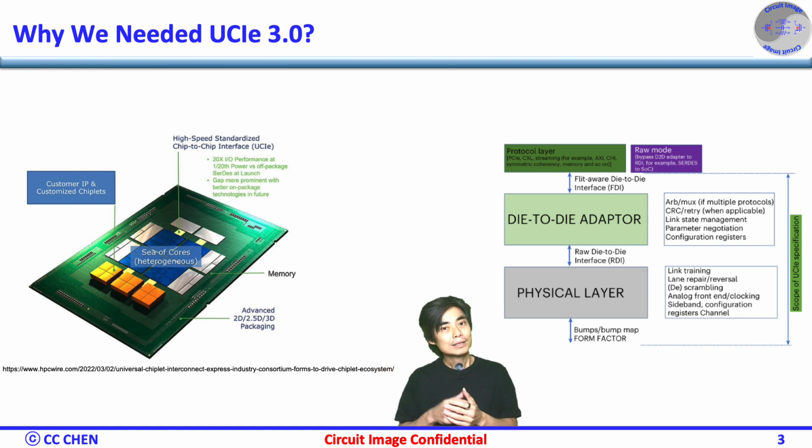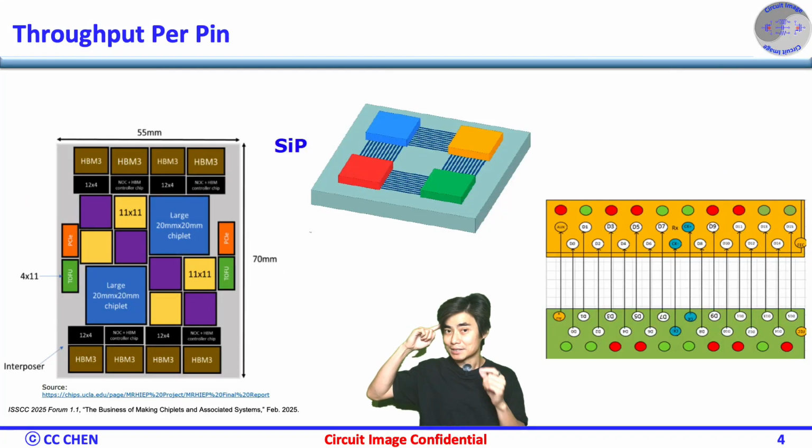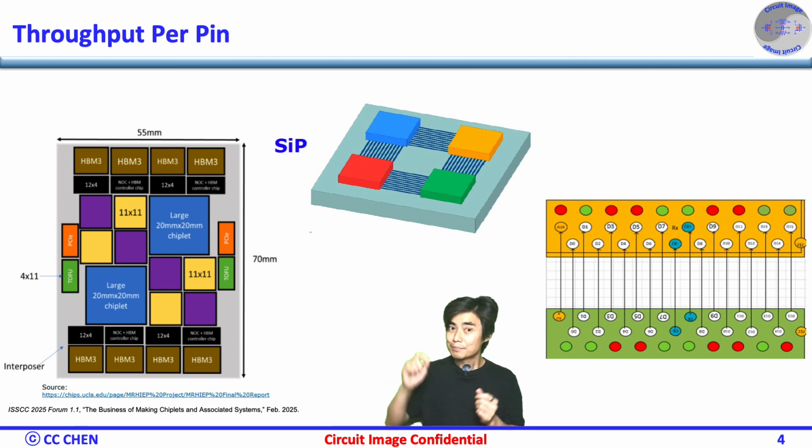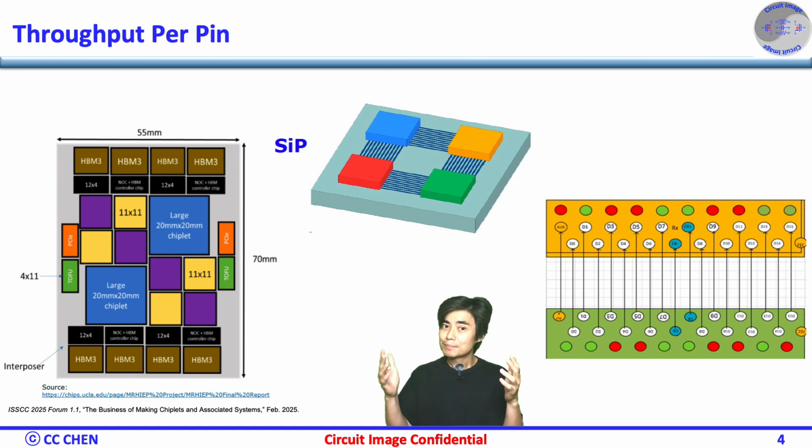With that in mind, here is what 64 gigabits per second would buy you. Think of 64 gigabits per second as the lever. With the same pins, you get about twice the bandwidth, or you can keep the same bandwidth with roughly half the length. Shorter length makes routing easier, cuts crosstalk, and relaxes the power network, great for memory and accelerator breakout. The result is much better bandwidth density, where pins are the bottleneck.